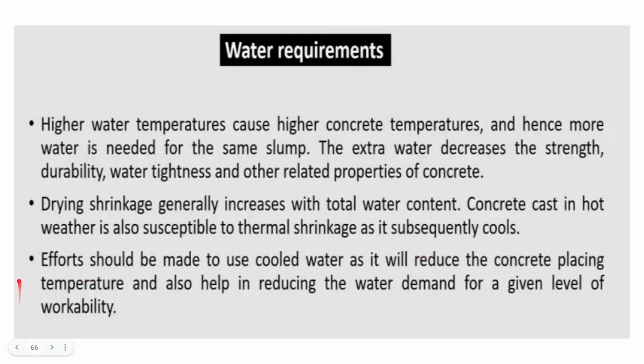Effort should be made to use cooled water as it will reduce the concrete placing temperature and also help in reducing the water demand for a given level of workability. So cooling of water is one of the very imperative conditions which can be used.